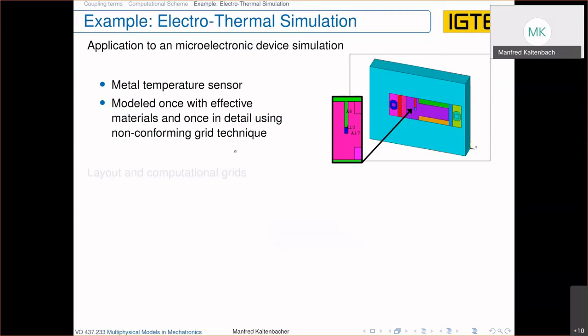And so it is important that you also include with any complex electronic circuit a temperature sensor, which is used as a monitoring sensor concerning the temperature, and then you can decide if you switch off your, for example, power electronic device in order to protect it from too high temperature gradients within your device, and therefore perhaps having a problem with too large mechanical stresses in such a device.